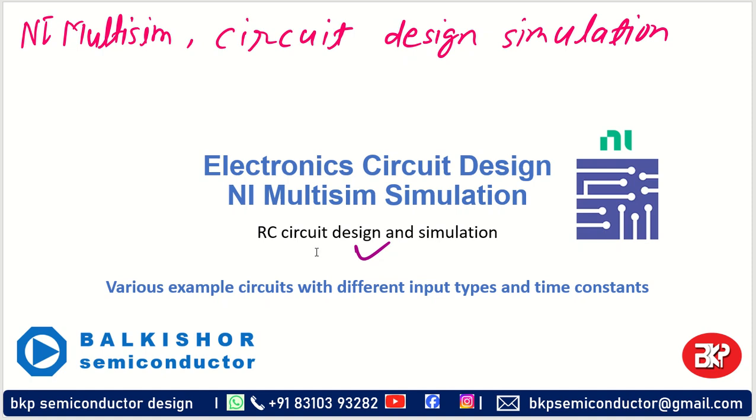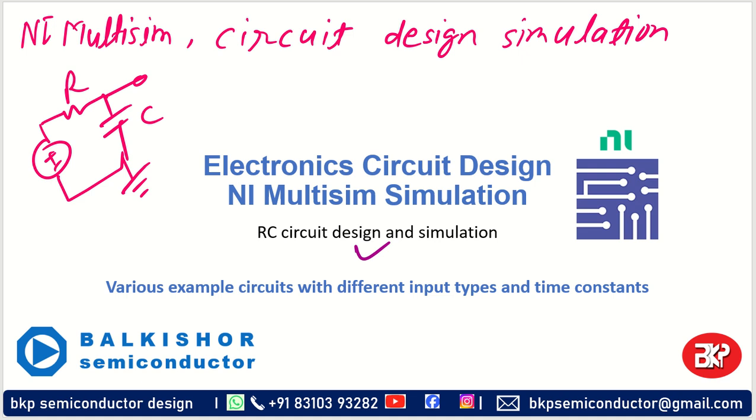Namaskar, my dear friends. Let us talk about how we can design an RC circuit and how we can simulate it in NI Multisim. We'll take a very simple RC circuit, give it a pulse signal, and see how the capacitor charges and discharges because of the resistance that we are going to put. This is a very simple circuit that we will use.